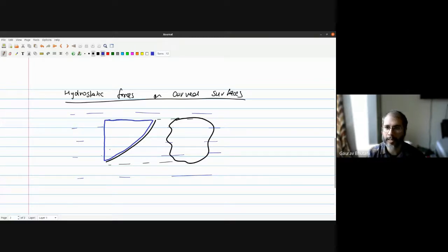So the system is under equilibrium. That means the net force and the net torque acting on the system is zero. So that means that the net force acting on this hypothetical thick blue liquid volume that I have taken is also zero. Now on the right surface of this fluid volume, you have forces acting. This liquid volume applies force on the curved surface, and the curved surface then applies forces on the liquid volume. Of course, when you go down, it increases. So it's something like this.